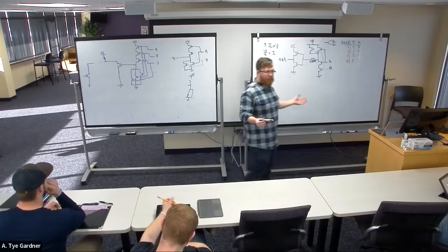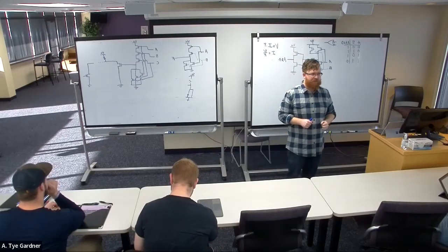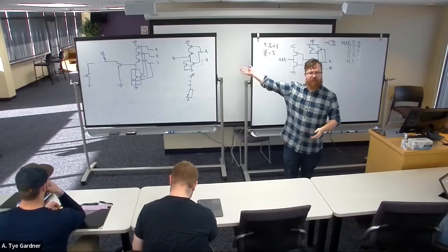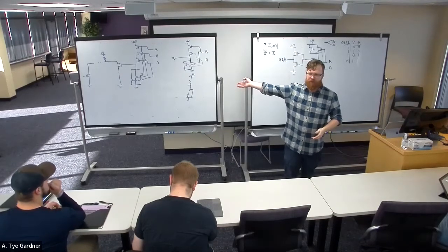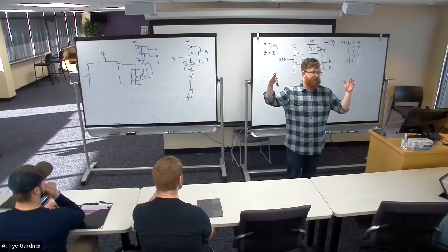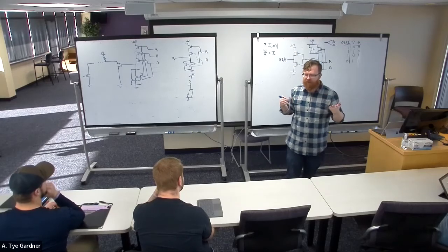And now in order to make a 1, they just don't make a 0, right? Because it gets pulled up. If I close that NMOS device, then it makes a 0. If I don't close it, it makes a 1. If they both close, they're both 0, nothing breaks. They're not really talking to each other.